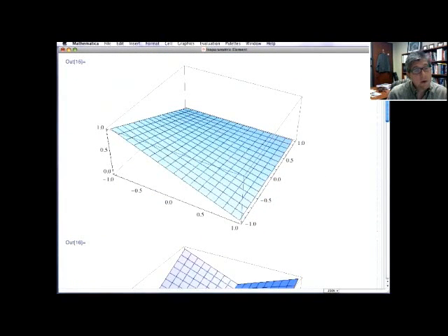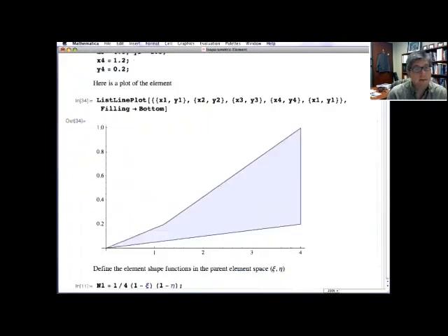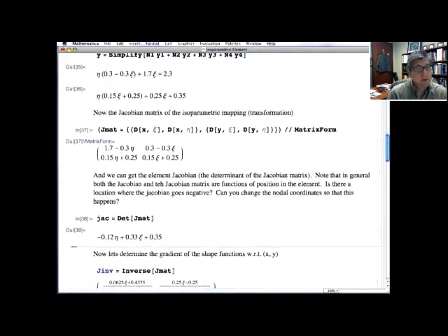Psi equal to -1, eta equal to 1 is up around node 3, and that makes sense because that is the one that we pushed through. So you can see that gives me a problem. That would give you the negative Jacobian. But there's still regions where the Jacobian is positive, right?